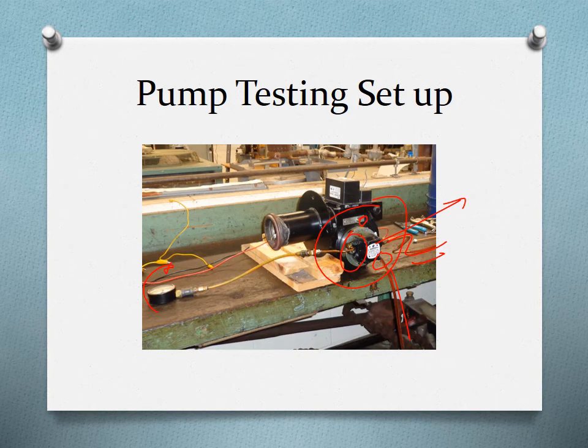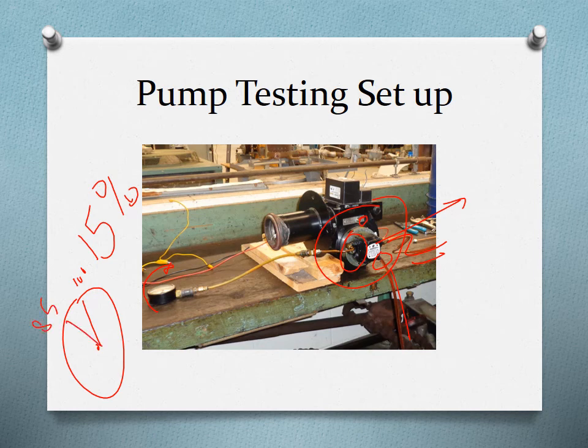And to know if the pump is not faulty or it's not leaking, you can turn off the power, and the pressure here should drop by 15%, no more, and stays there. So the pressure will be, for example, here at 100 when it's on. We turn it off, it should be at 85, which is 15%, and stay there and not drop. If it keeps dropping, that means something is wrong with the system and there's a leak in the system.